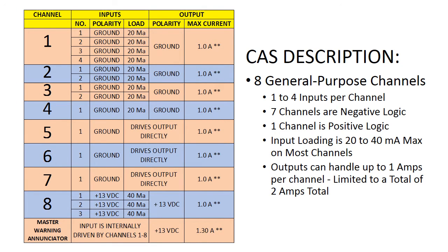When you do a self-test of the circuit board, you will turn on every single relay and every single output warning light. If you're using 80 milliamp panel lights like I am, the total load during a test is 1.3 amps.